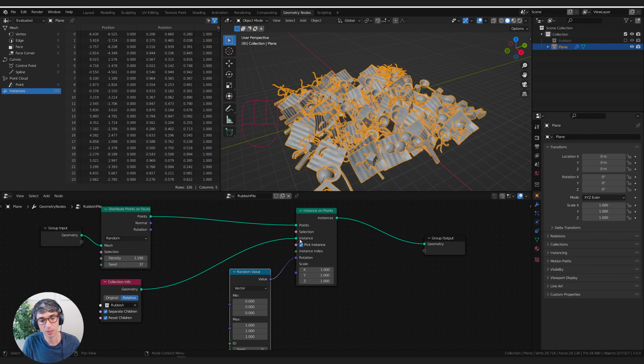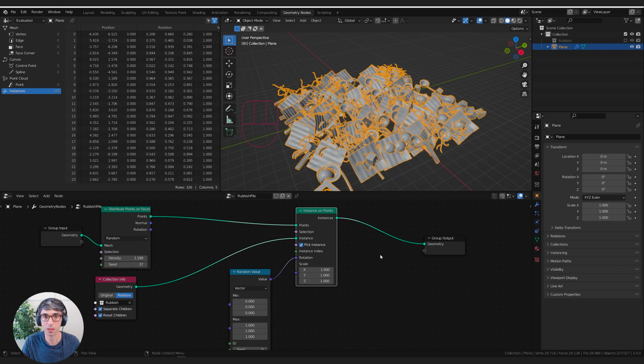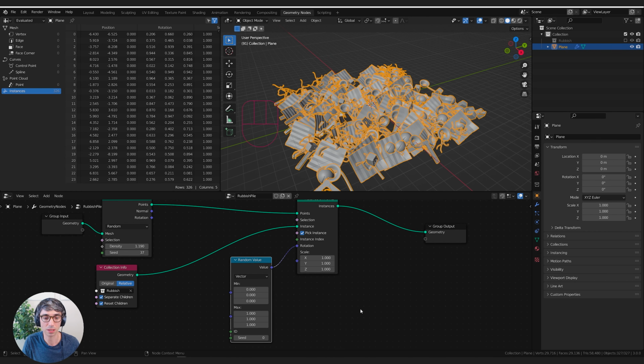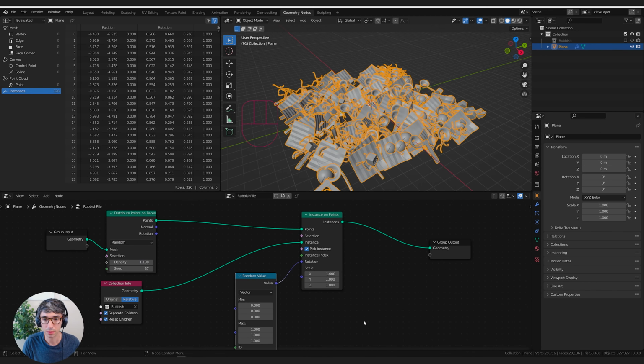Whereas the solid line means it's not going to do a loop. It just does one thing. It takes this collection and sends it over to here once. Now this thing has that collection. There's no need to cycle through anything because it has all the info it needs. Whereas in this case, we need it to cycle through everything. So that's what the dotted line means in the new geometry node system. Picture it like a loop where it goes through everything and applies the system that you've created to it, or changes values in a certain way. So that is how that works.